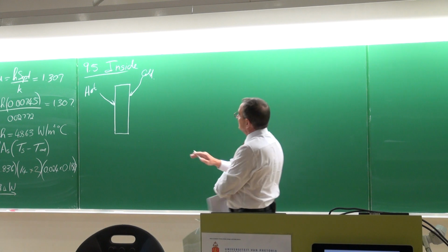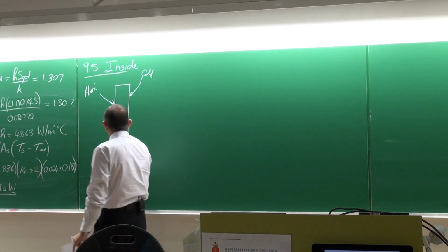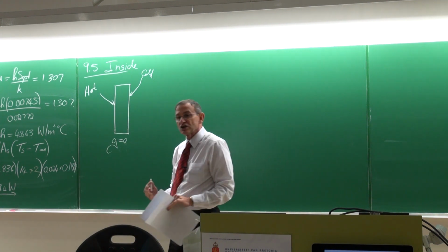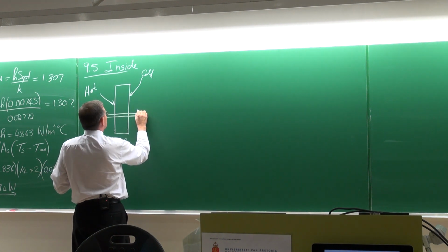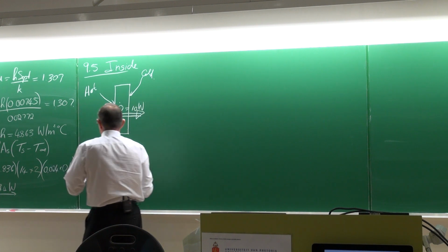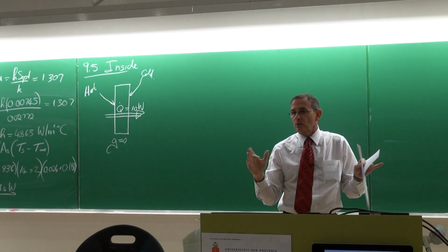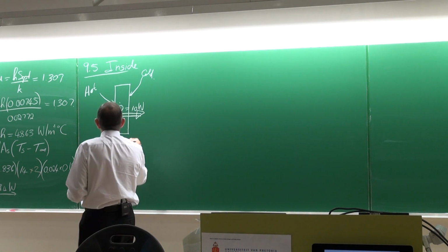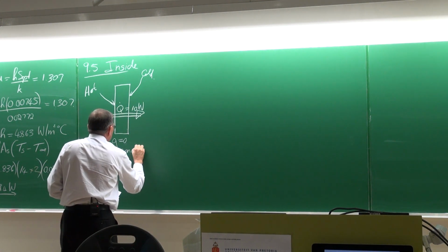Right, so if we've got the hot part and the cold part, and you took it up into space so that there can be no natural convection, then just as an example, the heat transfer rate would be approximately 10 watts. And this 10 watts can be 10 watts per square meter or whatever. So it means that this heat transfer rate is by pure conduction only.